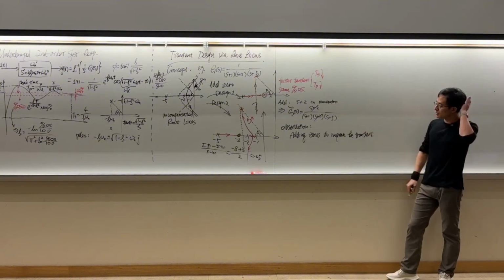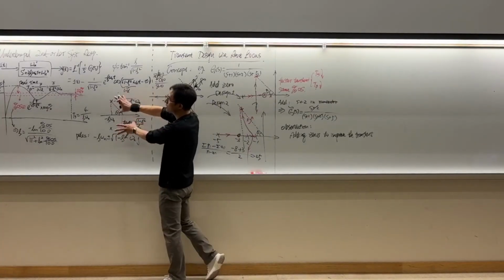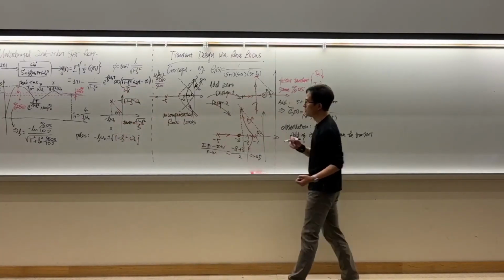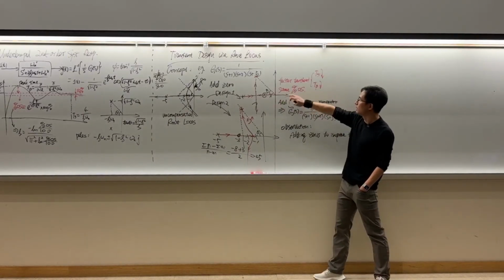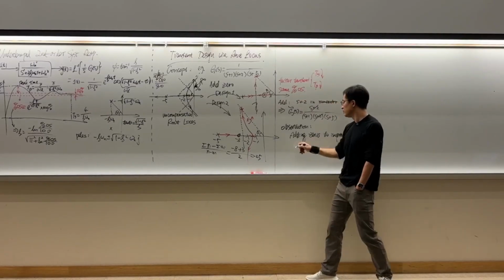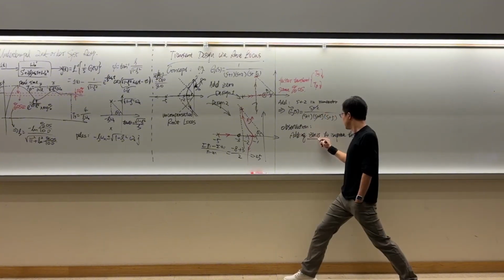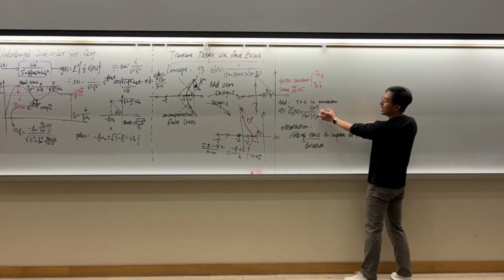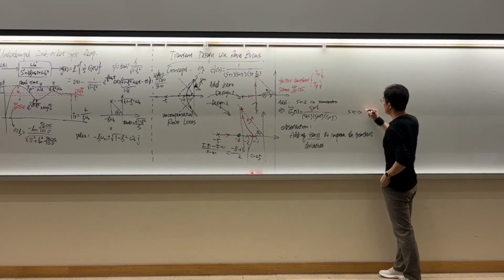Just a simple addition of the zeros, combined with what we learned previously, all the important concepts about second-order systems, can improve the transient while still maintaining the percentage overshoot, etc. This is called adding derivatives. Because adding zeros, since s corresponds to taking derivative actions in the time domain.